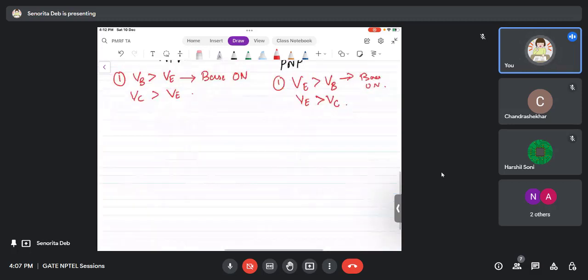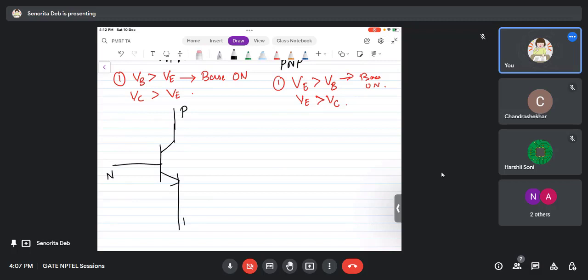So in a transistor, if you see, this is nothing but N, P, N, and if you see the Ebers-Moll model, you will see this can be connected like this, like it can be shown in this way. But two diodes connected like this back to back will not give you transistor action. It only gives transistor action in some cases. Okay, if you want to read about it, that is explained in Streetman and Banerjee's book. But apart from that, you have to remember, this is how it comes out to be, the Ebers-Moll model.